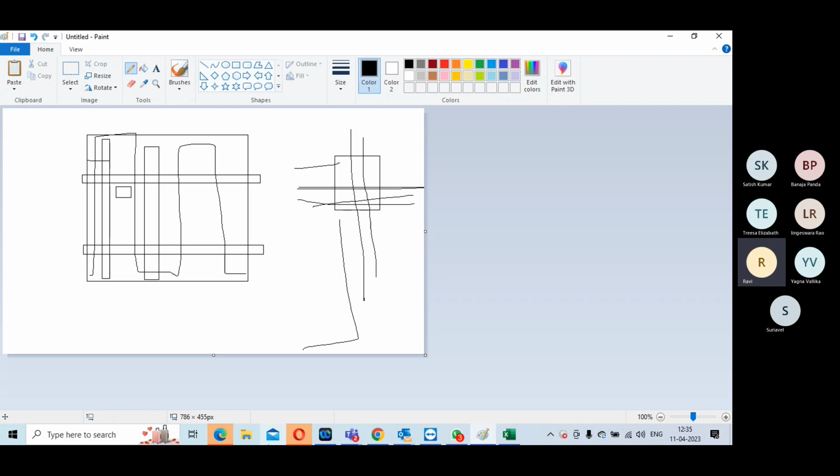You understand? In a multi-voltage and shut off design, you will have to have level shifter plus isolation plus everything. You understood? Now, where will you place your isolation cell? This is about power gate placement. And for the always on, you're directly going to hook from the main mesh.